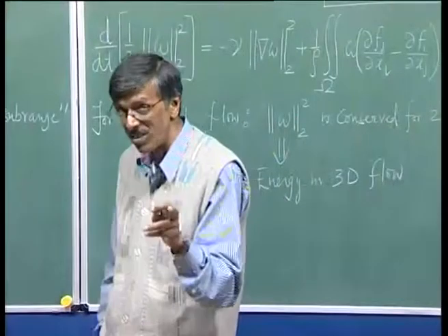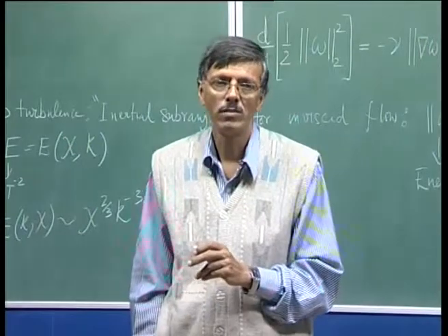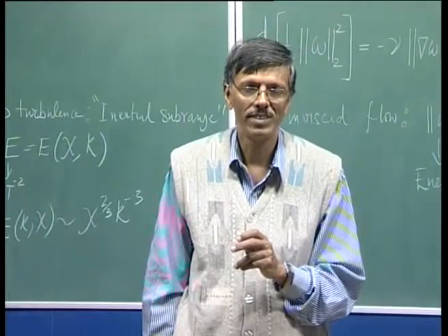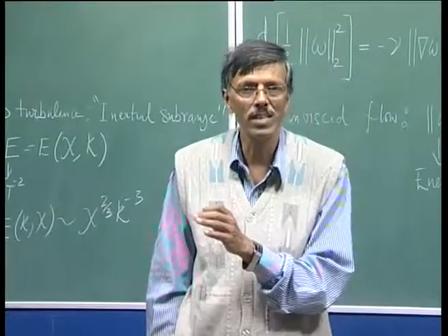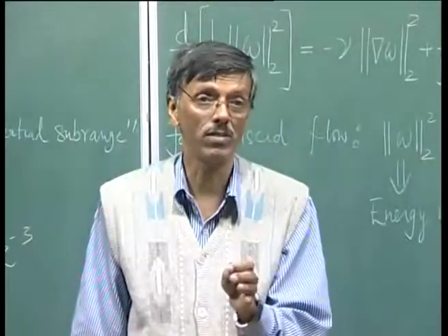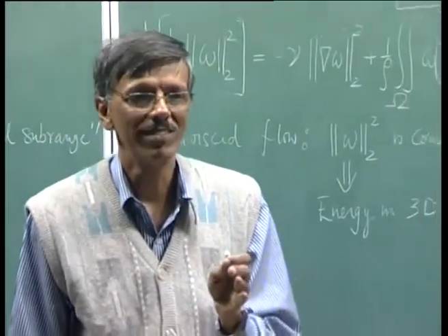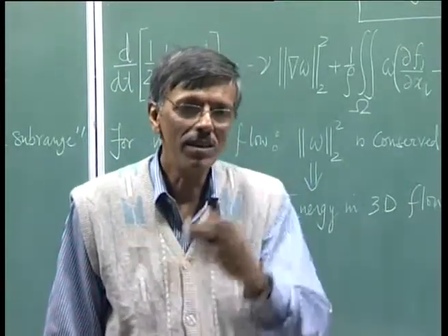If you look at the Blasius profile, what is the value of the second derivative of the velocity at the wall? It is a zero pressure gradient flow, and the second derivative is related to the pressure gradient. So, the second derivative is 0 on the surface, but that is not an inflection point, because an inflection point is one across which the slope changes sign, and you do not have anything across, you stop there.